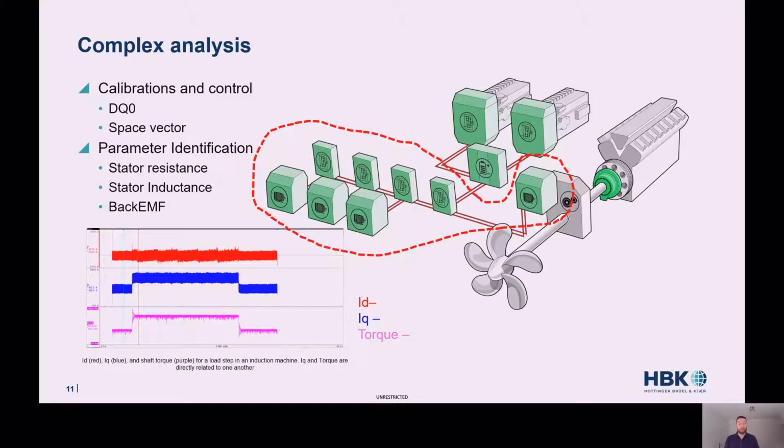When implementing motor control strategies, there is a need to get the motor parameters. These are usually stator resistance and inductances, and the magnet flux linkage or the back EMF constant. The stator resistance and inductance can be obtained rather easily with line-to-line impedance measurements for different rotor positions or through a short circuit test. The back EMF is usually obtained by means of a no-load test.